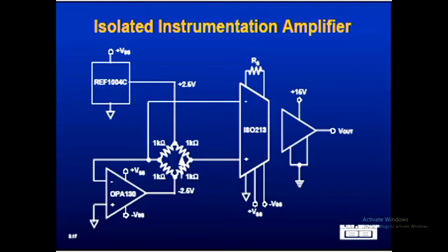So how do we get a virtual ground there? Remind me. At the OPA130 op-amp, there's a virtual ground between the inverter and non-inverter. Correct. And that tracks back to that point in which we release the bridge. Okay, so this is going to be 0 volts here as a consequence. All right. So if this point is 0 volts and this is 2.5 volts, this is a symmetrical bridge.